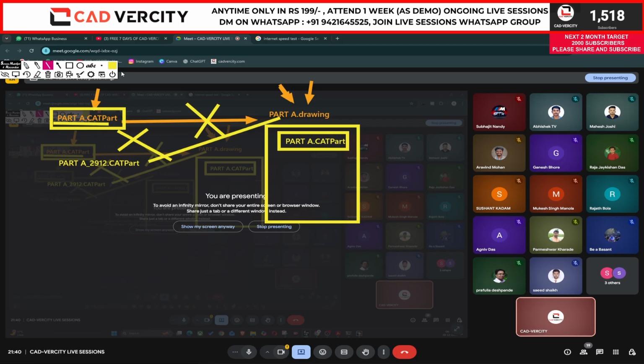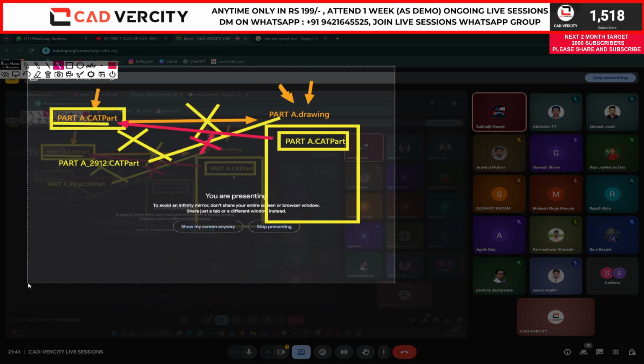Now the link is broken. Why? Because in this drawing you have taken the views from the original file, not from this one. Got it? Clear? Yes, sir. Perfect. Okay, good.